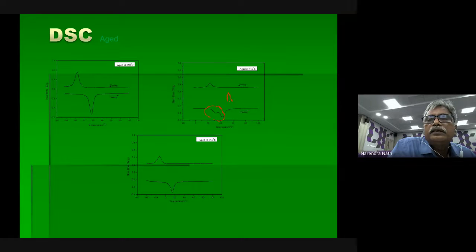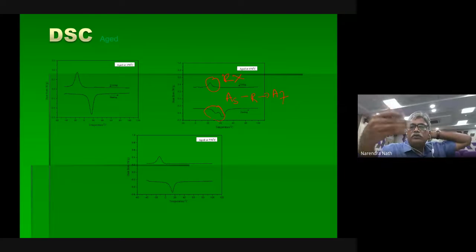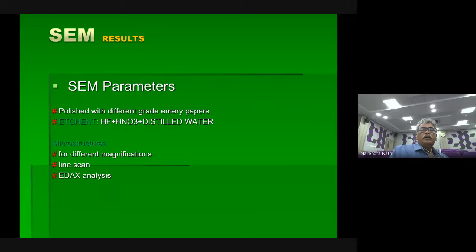Now it is heating. When it is heating, austenite starts, reaches rhombohedral, then austenite finish. Whereas here there is no R. In some cases, in both cooling and heating, R may appear. So this all depends on what the processing history is and what the cooling history is, what the heat treatment history is. And SEM results. So here, very clear, no need to explain.